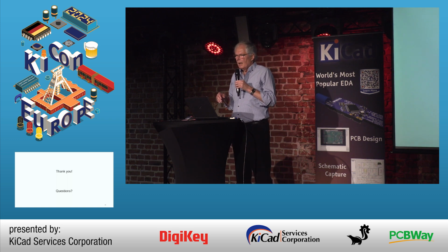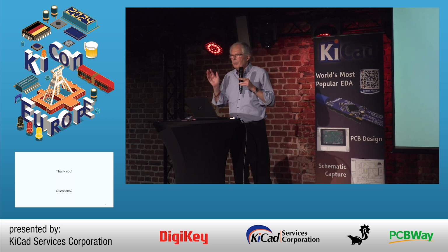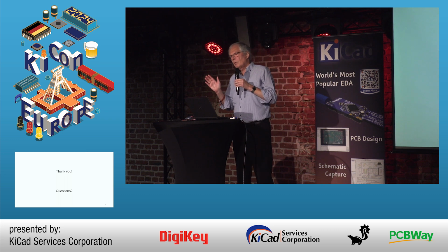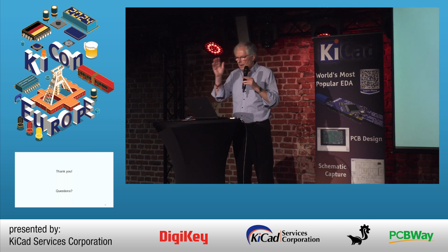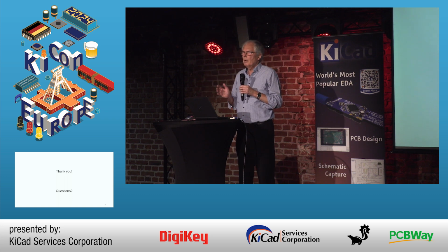And often, if you are new to simulation, it's not a good idea to start with simulating the whole thing. This will typically never work. You have to simulate blocks. And then, of course, one has to consider how to do that. I think the best is then you cut out these blocks, copy them, and put them into an additional small simulation project.